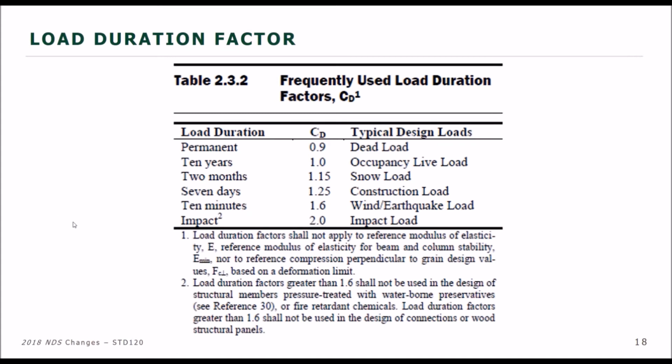Okay, also for the load duration factor, we've clarified that the load duration factor, C sub D, for impact, the 2.0 impact load, does not apply to wood structural panel. And this is just a reflection of what the industry recommends. That's just shown here.